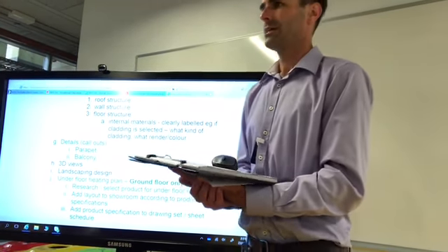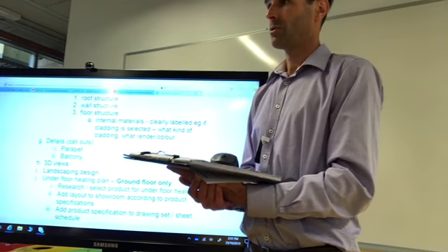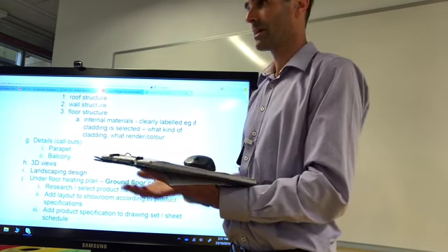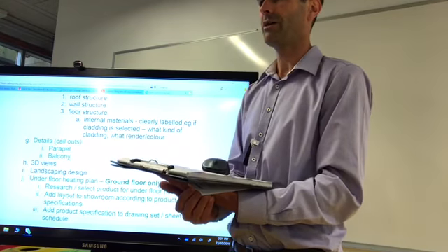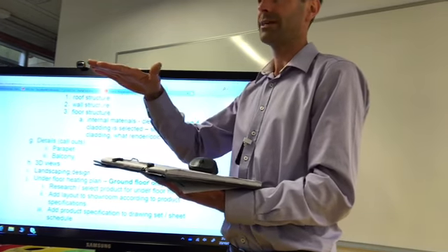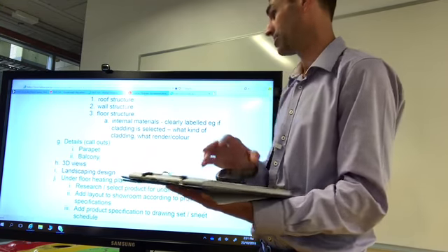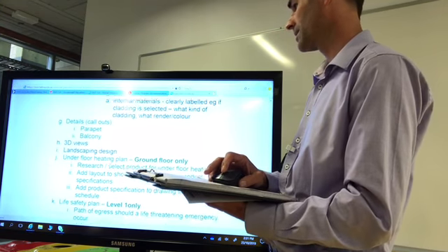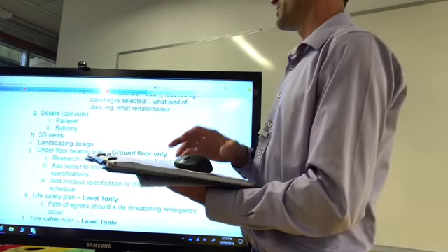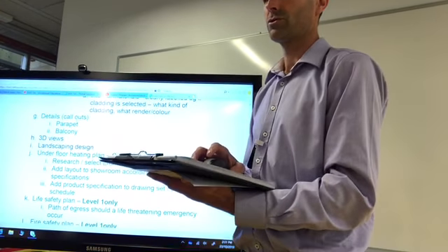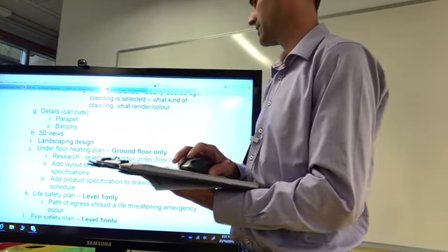I think that's also going to be a simpler detail to draw, because it's about carrying that concrete floor out and providing a set down in that and a slope on that to meet your drainage. So this is what we're going to have a look at today, and have a look at the resources and the thinking around that, just to get you started on that.